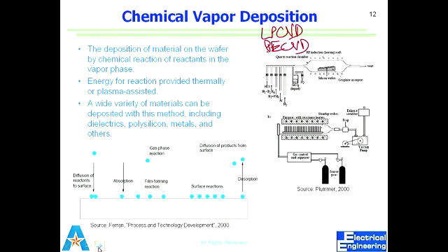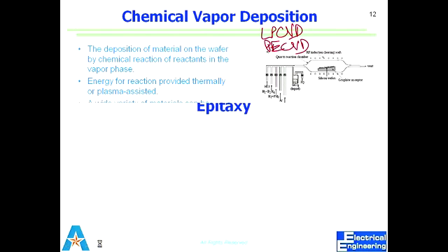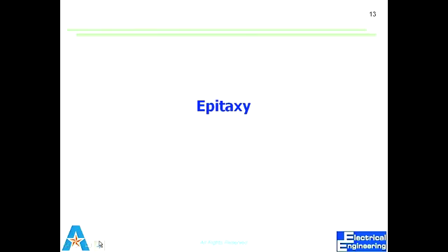Yeah, so it starts with very low power, and then you gradually get to your actual power that your recipe requires. Right? So these two, PVD and CVD, do deposition of amorphous materials, amorphous without any crystalline structure.